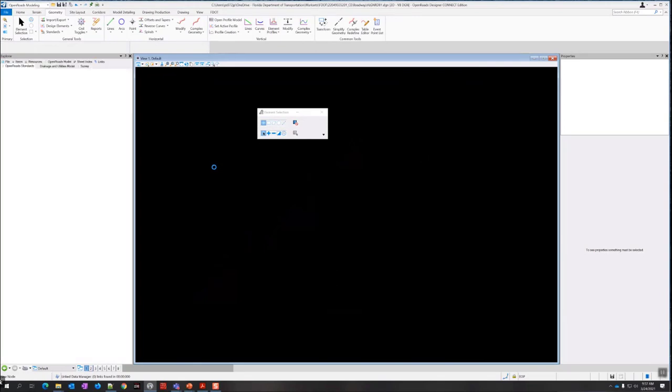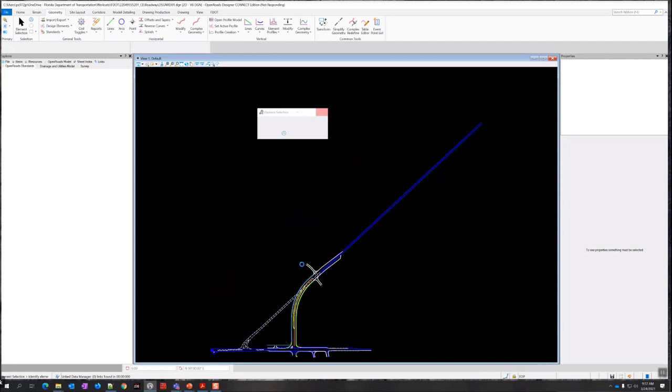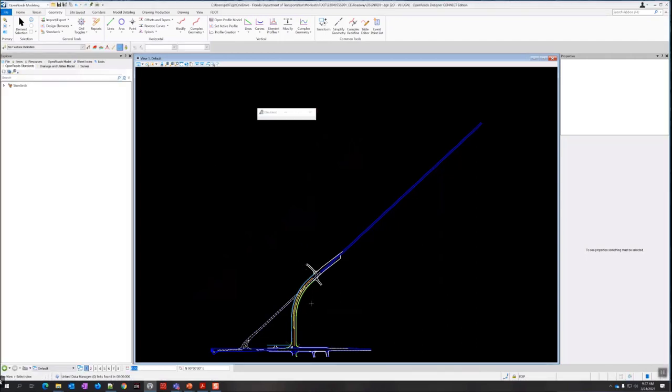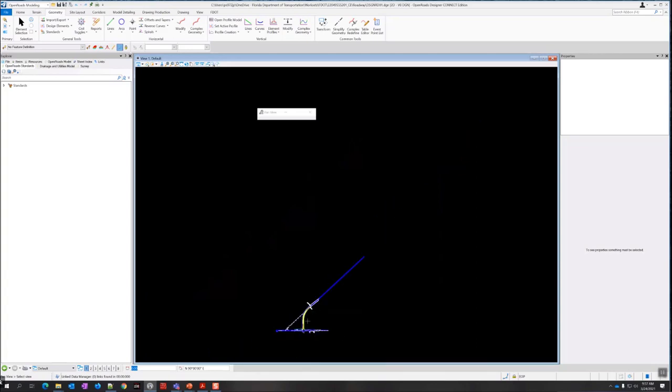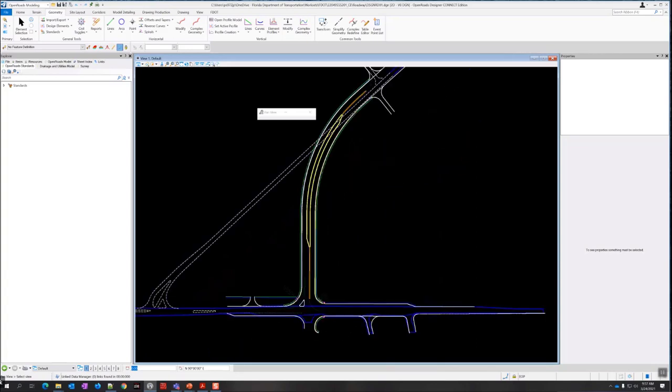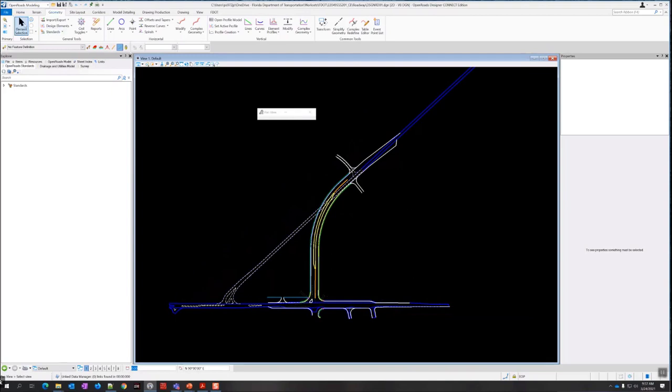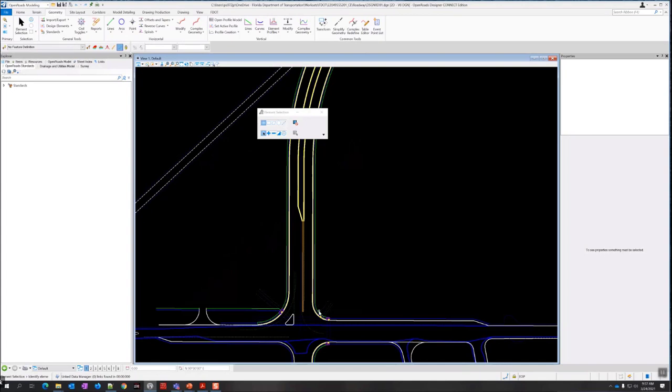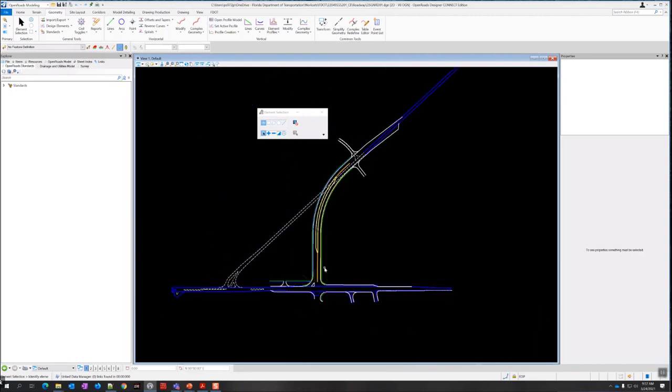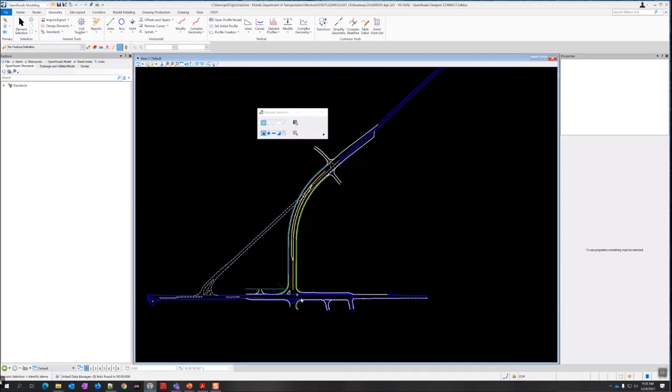So for this one, we just basically need to simplify. There's a couple steps we've got to take just to simplify it. And then we're going to export it. Essentially, we're going to create a fence and simplify it, because we have a lot of things with civil geometry, but when we're creating these AMG files, basically all we want is MicroStation geometry. We want simplified CAD geometry, so it's a more universal format that they can work with. So we're just going to be stripping all the intelligence, essentially.